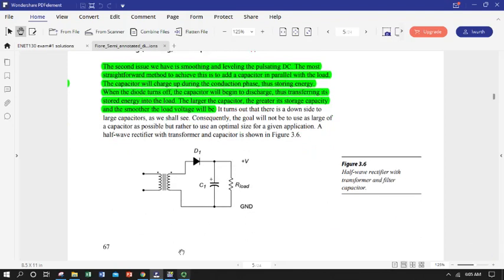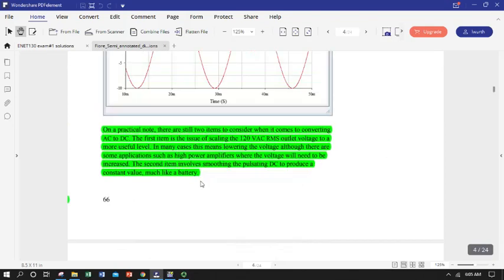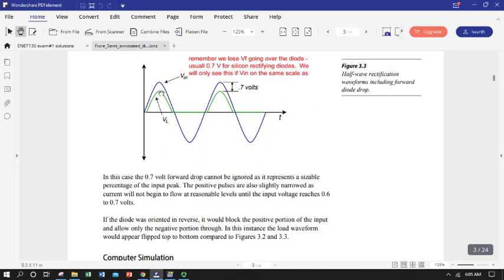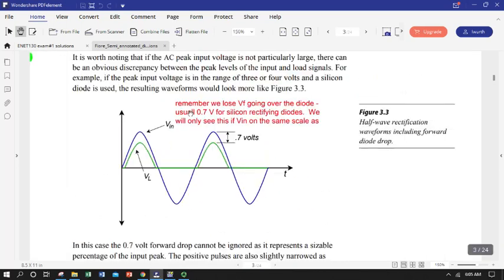So as we mentioned with our Tina output, let's go back to our waveform output here and blow it up a little bit. What we really want, we've got our green curve coming out of our diode, and it comes up and traces our input, but then it doesn't stay flat. It goes back down and then shuts off for a while. So ideally, if we wanted true DC, we want this to stay a flat line.